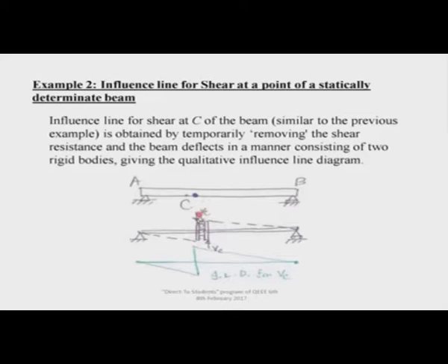Definitely this shear force is making this part go down. That is why, to me, this VC, which is the shear force at C, is positive according to my idea. Next, this V is also pushing the left part up according to my sign convention: left up and right down. It's left for this portion and right for this portion. This is actually a positive sign convention for me.